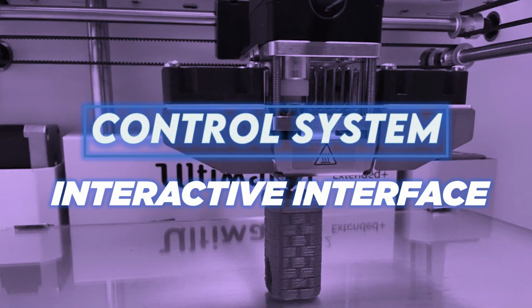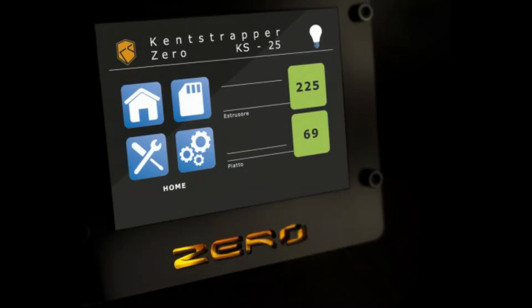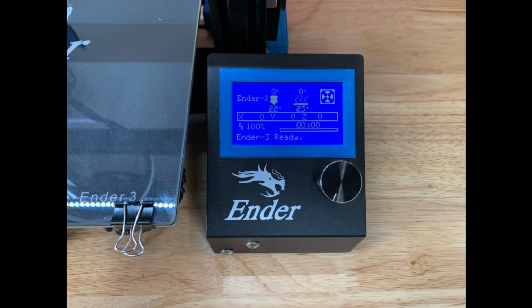the means for getting the job files queued for fabrication, an interface menu or other UI strategy that an operator can navigate to achieve the intended goals, and maintenance utilities, usually within the interface menu itself, which allow an operator to update firmware, perform initial or additional calibration stages, and manage materials, loading and unloading, and profile setting, and other aspects related to the baseline of the machine.